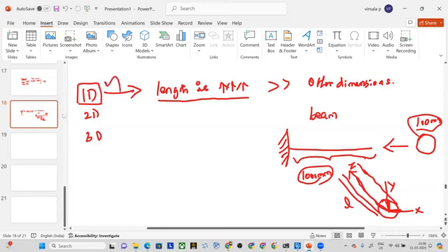This actually will make you a professional because everything is 3D only. But if you do the 3D meshing for all the components, then unnecessarily you are increasing the computational time. Computational time in the sense, after you click on the solve button, you might have to wait for 2 to 3 hours for solving a beam problem, because you have given a 3D mesh.